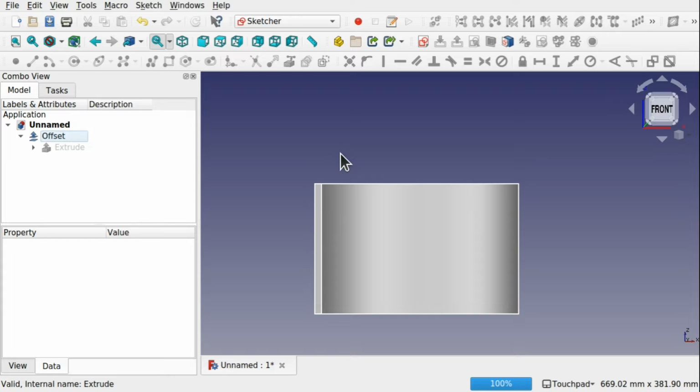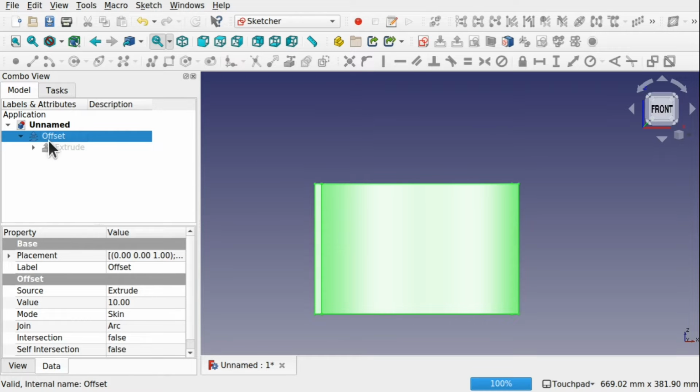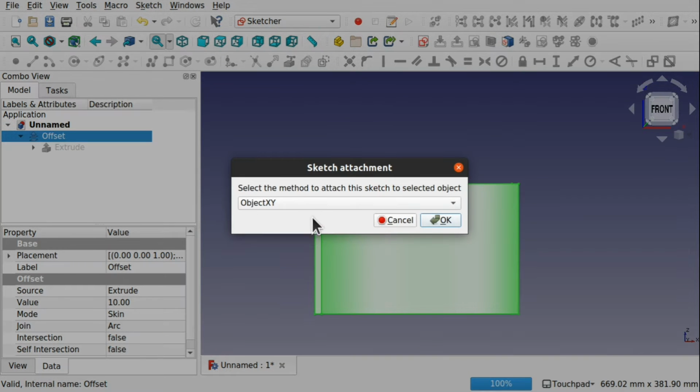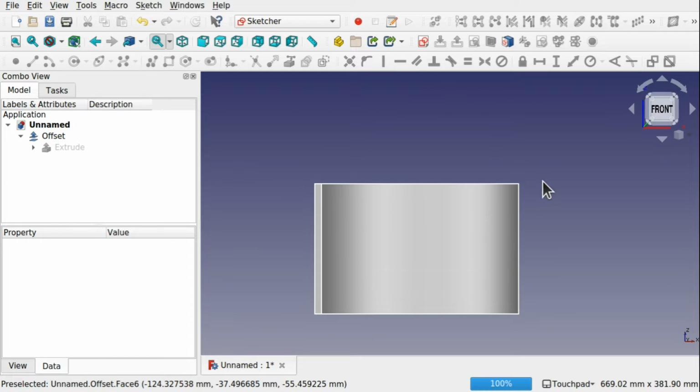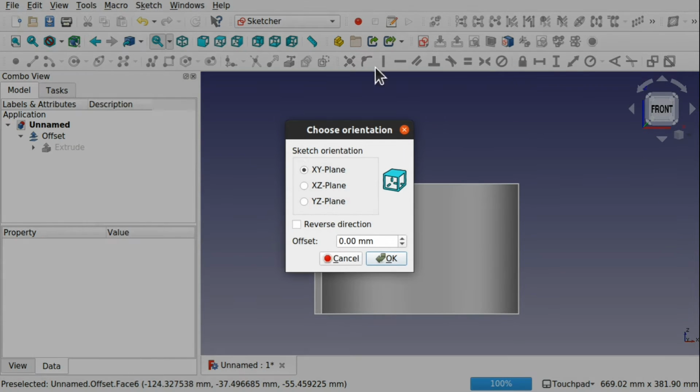Let's delete that sketch. The same if I've selected it on this side and hit sketch, it's going to ask me what plane. Now I don't want to use that. Make sure nothing's selected, and click the sketch, and I want to place it along the XZ plane.